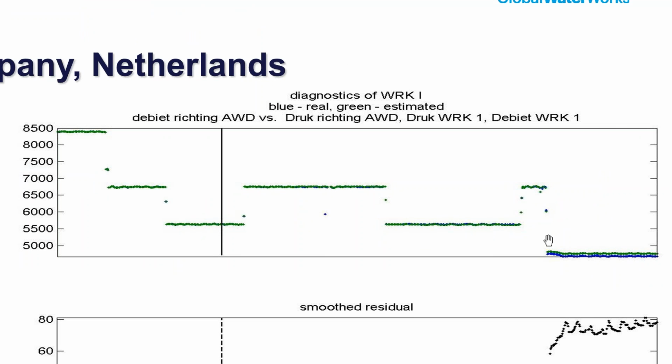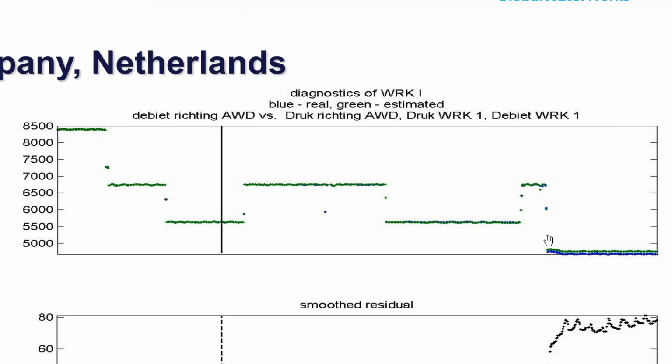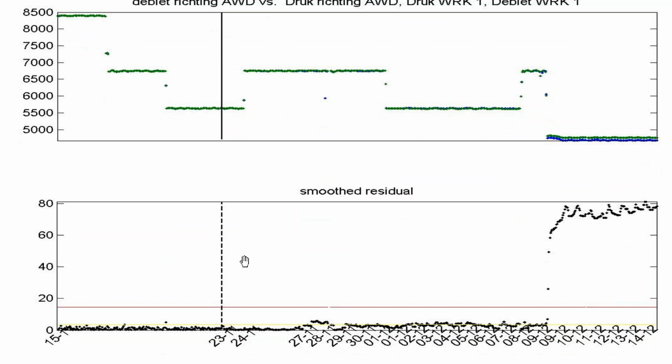Now, let's see what we did for the testing. The lower chart is the testing. After we trained the algorithm, we started looking for the leakage or the critical failure. Now, the y-axis again is flow, but look what happens here. This is the leakage. And as you can see, it's on 80, meaning 1% out of the maximum flow inside the pipeline.